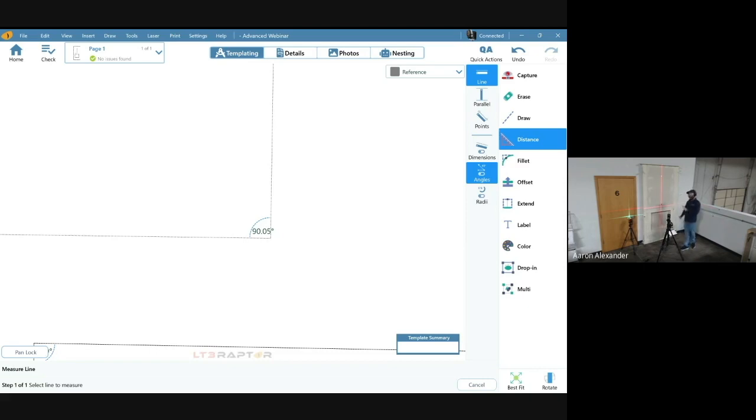When you're dealing with a fireplace that's 2 stories tall, we're going to want to make sure we're really tight to that 90 degrees, because based off of how accurate that is determines how many feet and how much variation you could have. Okay, so the taller the piece in a vertical situation, really the more accurate you want to be on creating this 90 degree here.